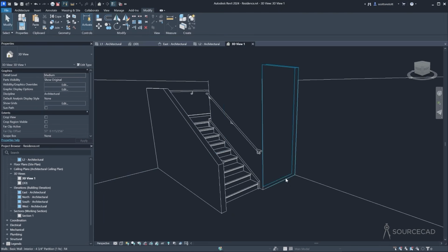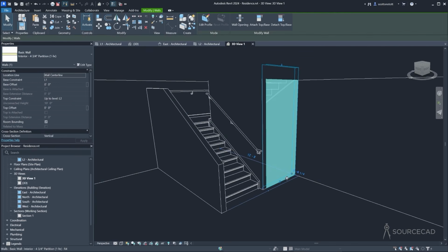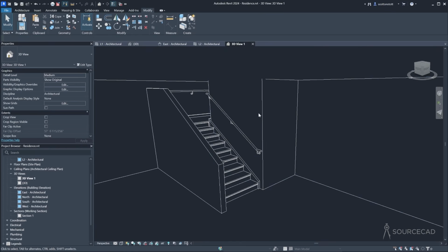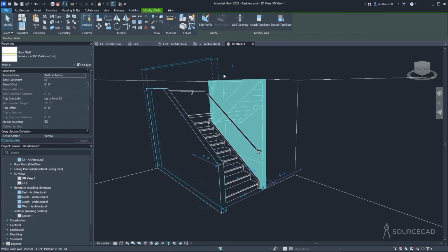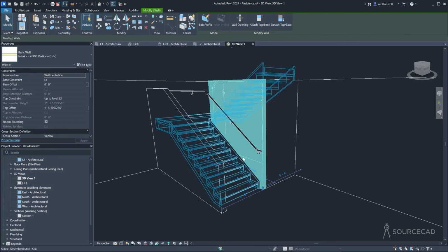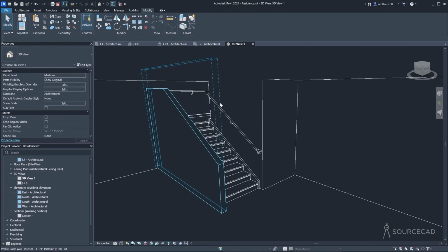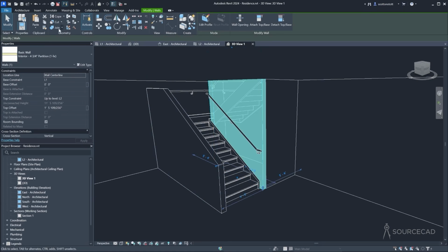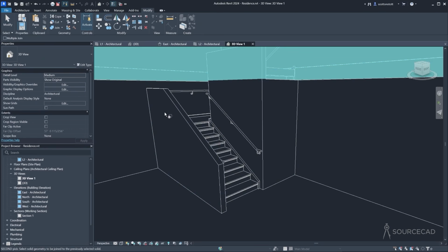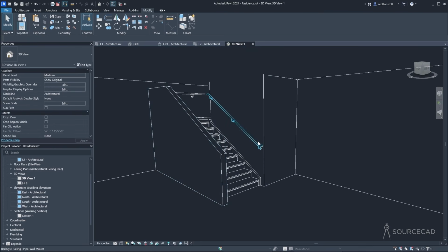Another thing is this wall here should actually end when it meets the floor above. So I'm going to attach that to this floor. And then Revit draws in a line there. This one here, this wall here, do I want that to go up higher? Yes, I think I do. I want this to go up higher. And we'll deal with that when we get up to the next floor. But I'm going to join this together with the floor, and then we'll get a line of intersection there. Well, we're not at the moment, but we will later.